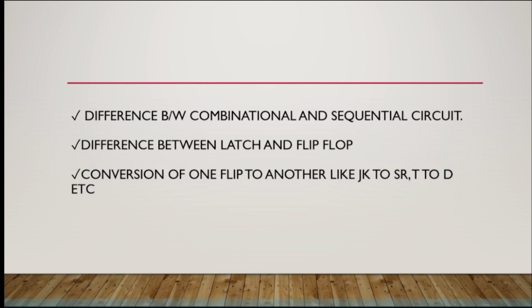And then coming to the sequential circuits. As I told you, you have to know the difference between combinational and sequential circuits. And within sequential circuits, the most important concept is flip flops and latches. So you need to know the difference between a latch and a flip flop. After that, you need to know the different types of flip flops that we use.